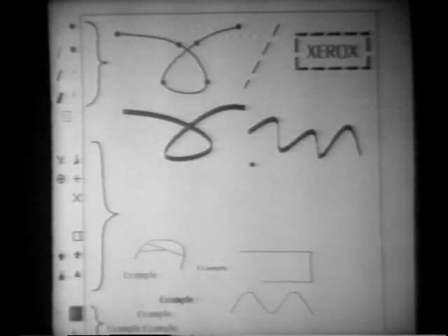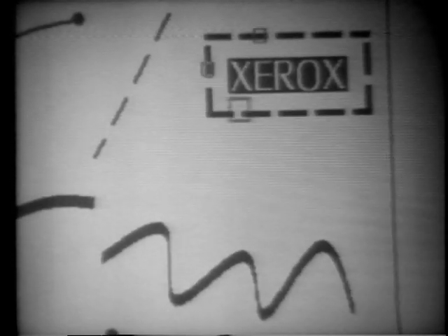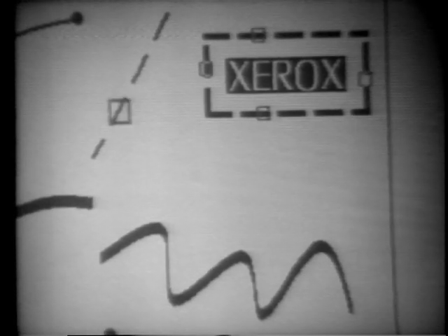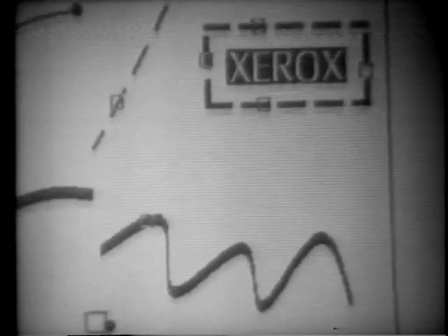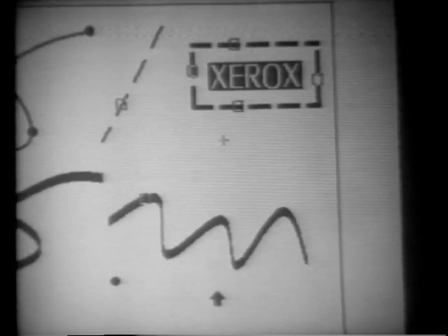Curves and text may be moved around and duplicated. First, objects to be moved have to be selected with this command. Selected text is displayed on a black background. Selected curves show a small square symbol. Then selected objects may be moved with this command. A move is specified by 2 points, which define the moving distance. For instance, move from here to there.